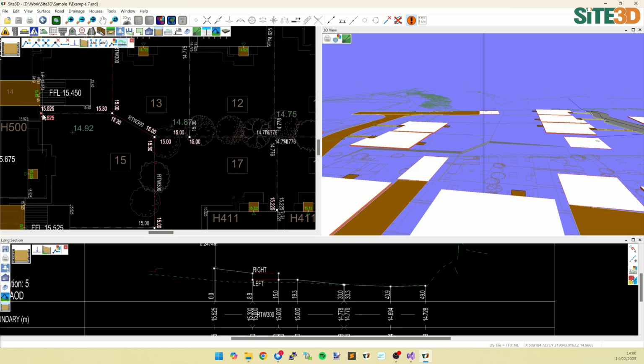So the left hand side in chainage direction that we picked is lower than the right hand side. The start position is where zero chainage is going to be. So the right hand side will be on the southern side and the left hand side will be on the northern side in this particular instance.